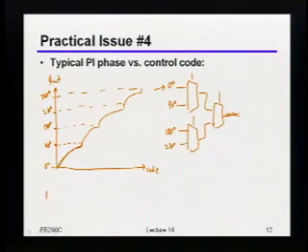say when you're flipping between 90. So first you're initially interpolating between 0 and 90, but then you want to flip to 90 and 180. If that delay between those two signals changes, then that step is, yeah, that's absolutely correct, right? If there's some mismatch in these paths, that's going to cause this jump, okay? So indeed, if there's some transistor mismatch, that would exactly cause this problem. Turns out, even without transistor mismatch, you will typically get this problem.